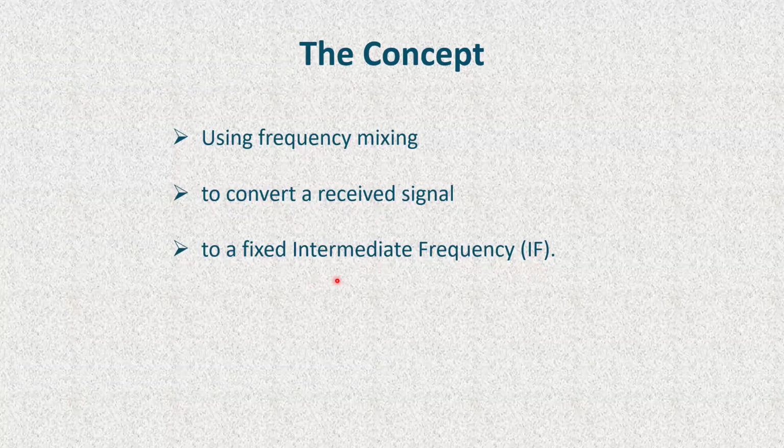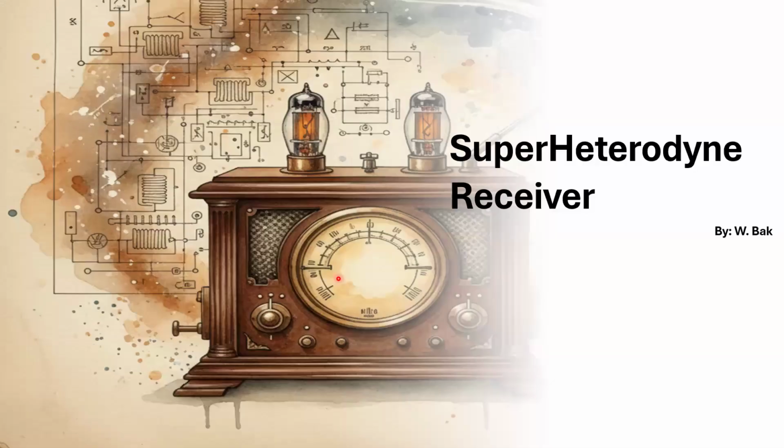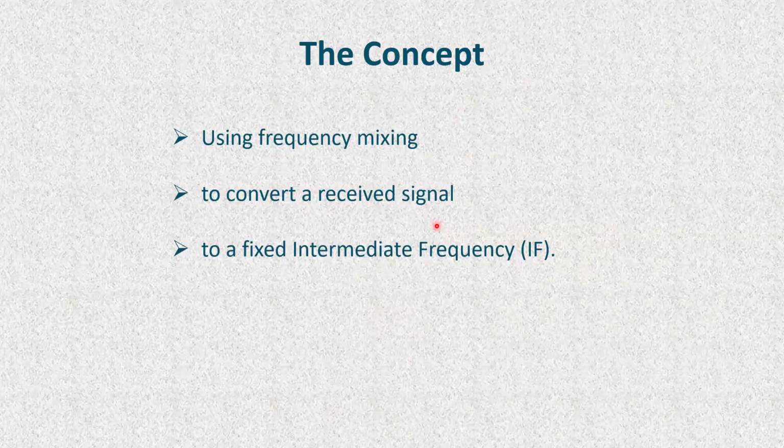The concept of heterodyning is basically mixing, combining two frequencies on a nonlinear device, in our case, and coming up with the outcome frequencies that would be the sums and the differences of the frequencies that were introduced to the device.